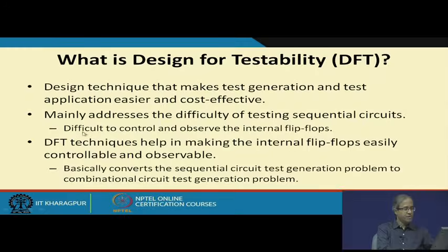So, the main issue was that it is difficult to control and observe the internal flip flops. Essentially, the DFT techniques, one of which we will be discussing here, try to make the internal flip flops easily controllable and observable. Controllable means we can initialize them to any value we want. Observable means we can see or read out their values whenever we want.